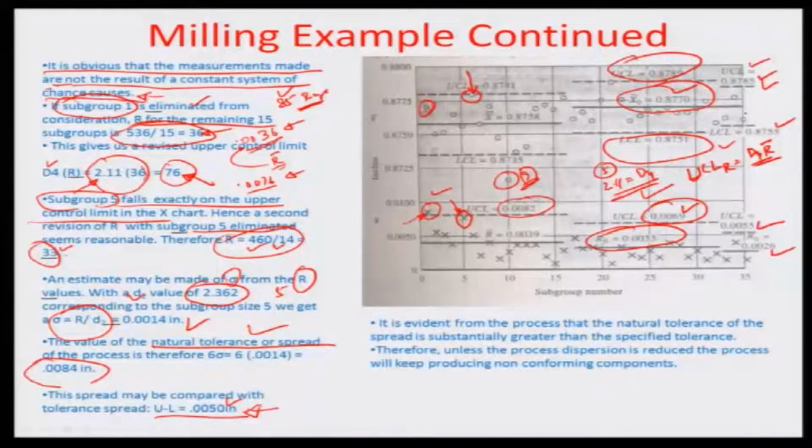of the X bar. So that is how you keep on modifying and changing the control chart iteratively as the situation may be, and finally by removing all the outliers you arrive at the exact control limits, okay, and then as and when an outlier comes you have to revise the control chart so that the control chart can go for the exact process health and does not get offset because of the process rejects which are never a part of the system. Obviously if you have eliminated something from the system, that should not be used as production data, okay. So that part of that subgroup is completely neglected from being in question.